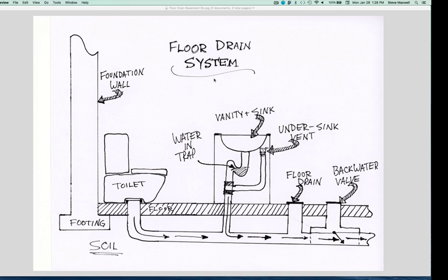And you're going to know you've got that situation because you've got a floor drain somewhere in your basement floor. It'll just be a round, usually perforated disc about 4 or 5 inches in diameter, and it will be a drain. So any water that's on the basement floor can drain down into it, but it's also connected to something larger and more extensive. So if you have a modernish sort of basement that hasn't had any plumbing rough-ins to it, you're going to have a floor drain like you see here, and that's just about it.